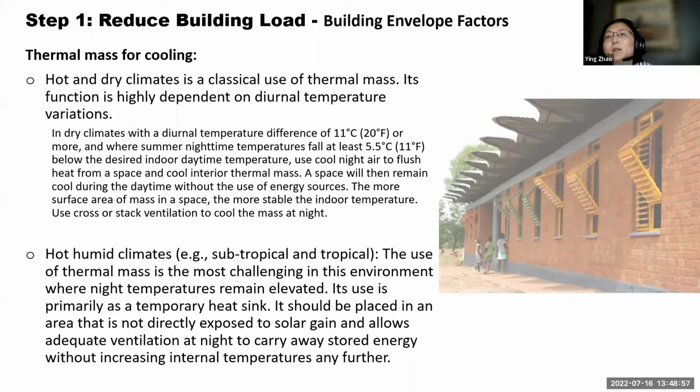For night ventilation, it is good to use cross or stack ventilation to cool the mass at night, because cross or stack ventilation is likely to go deep inside the building, so we will cover as much as possible of the indoor space.